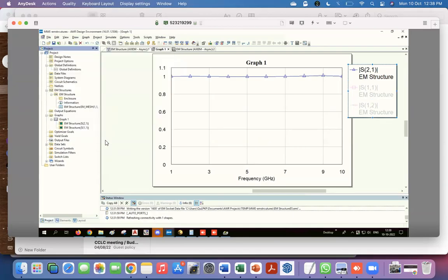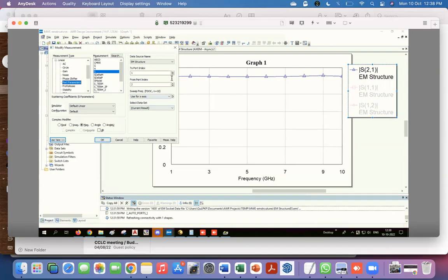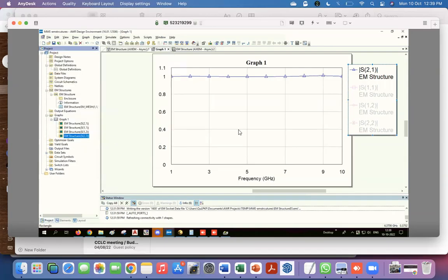Transmission in the other direction. Reflection of 4. So it hasn't plotted them yet, and I'm going to have to simulate. It's not going to actually re-simulate the whole thing, because once you simulate the EM structure with the ports defined, it internally knows everything about that system, which is basically the estimator. So plotting it again will not actually ask it to recompute the whole thing, so it will come instantaneously.